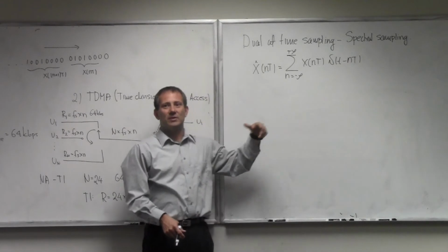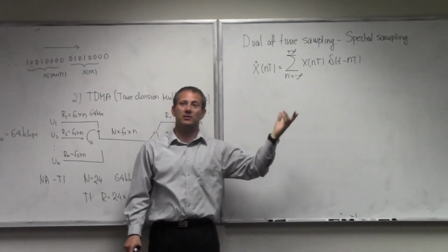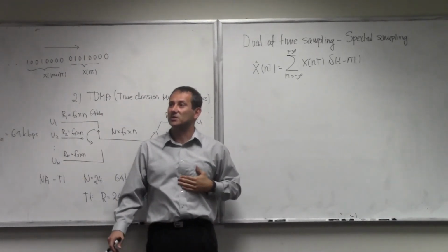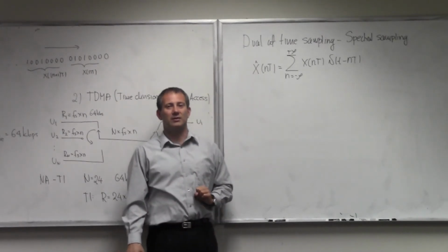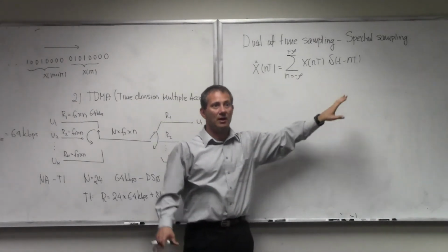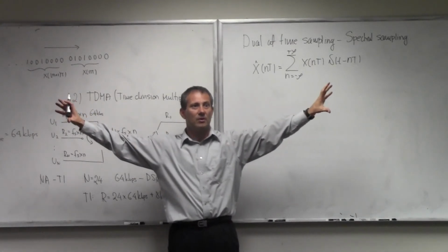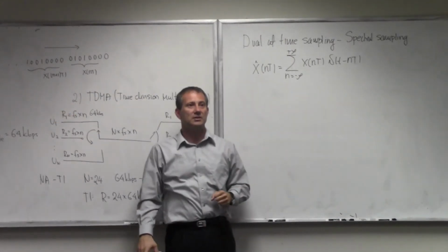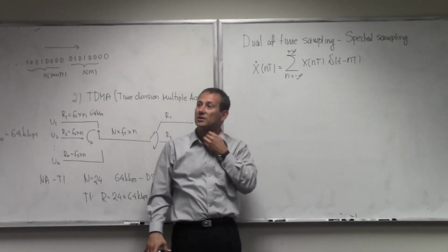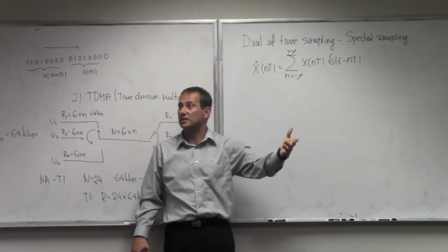Remember, we started from this and then we derived the spectrum of this. And we said, well, the spectrum of this is a periodic extension of the baseband spectrum in the frequency domain. And then we addressed your concern, and the concern was, well, what if it's not delta? Well, it turns out this can be any pulse chain, and as a result, this spectrum is not constant across the board anymore, but as you move further in frequency, it starts decreasing, as the Fourier series coefficients do, because what you're doing here is multiplying your x of t with the Fourier series.